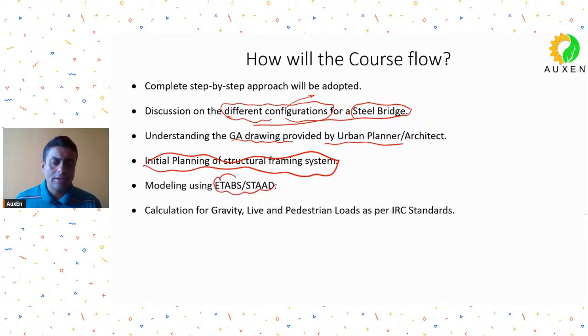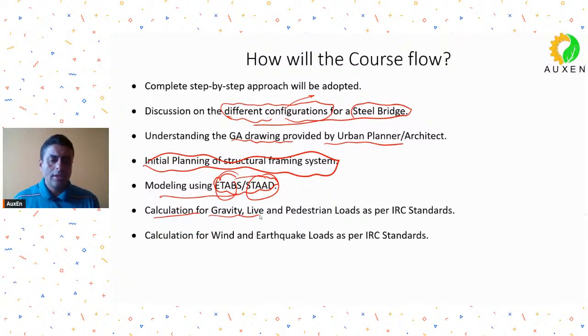So now I'll just discuss after a few slides whether to use STAAD or ETABS. Let me just discuss this point after a couple of slides. So we will do the modeling. Then, of course, the calculation for gravity loads, live loads, pedestrian loads as per the relevant IRC standards. We will also calculate wind and earthquake. Wind will be an important load for these kinds of structures. So we will do the wind load calculations as per the relevant IRC standards.